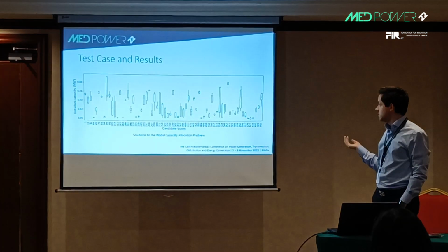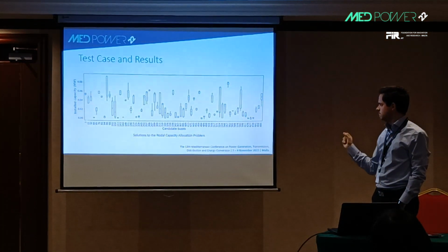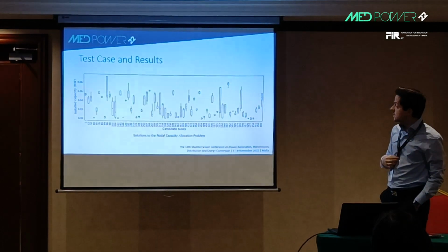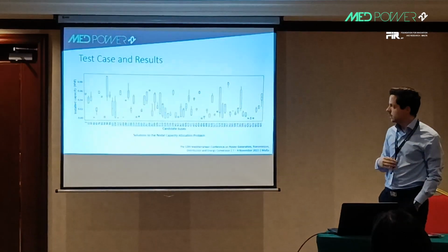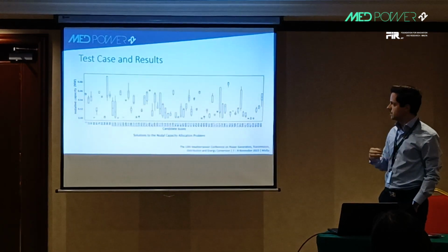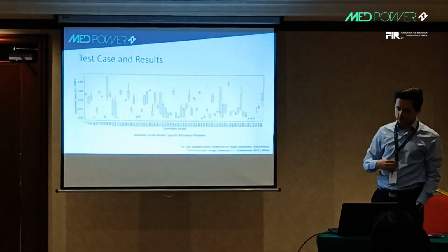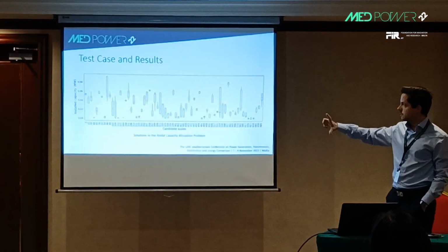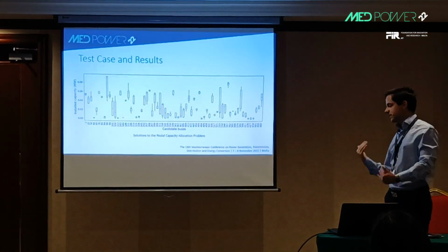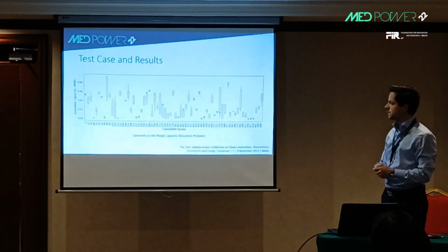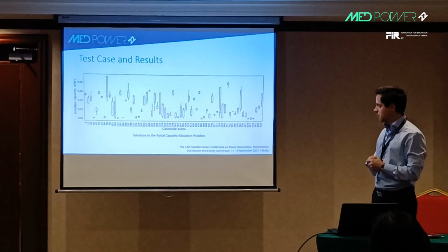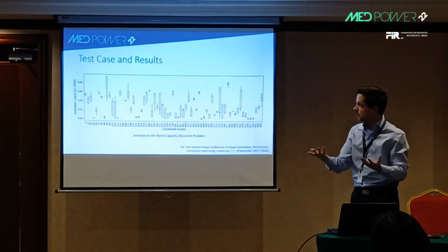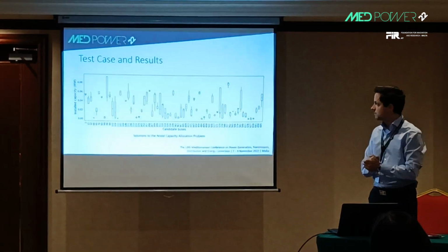So in every run of the genetic algorithm, they have around the same amount of power, which means that some buses are more independent, so to speak, in terms of power injection with relation to what's happening with other buses, while others, which have a wider range of possible solutions, are more constrained to what's happening on the other buses. Sometimes the algorithm favored that bus in detriment of others, and vice versa, while maintaining the optimality of the solution as a whole.